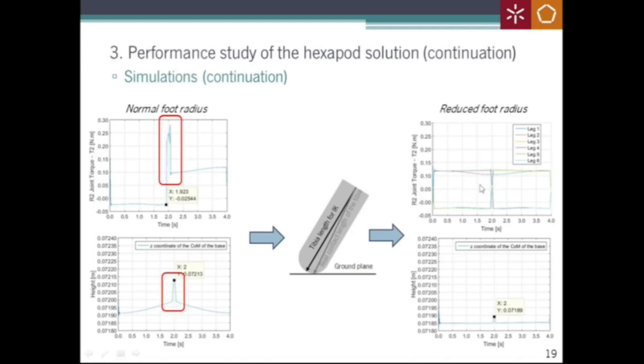In terms of simulation, this makes sense since the built robot has no compliant elements, and it is therefore a rigid structure. In reality, this is not true, since as the joints will have gaps and the servo motors will not respond immediately, the stiffness of each leg will be lower than the simulated one, which will allow a better distribution of the robot's weight by the support legs. For this reason, torque peaks were not considered in this phase.